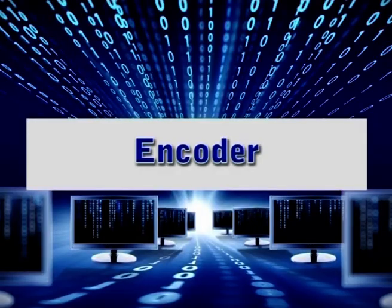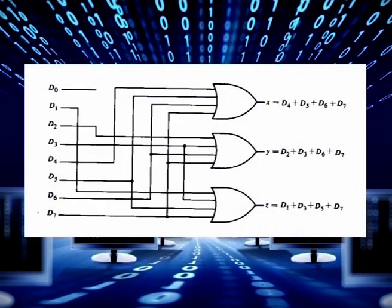Now, coming to the final topic for today, and that is encoder. An encoder is a combinational circuit which is designed to perform the inverse operation of the decoder. An encoder has 2 raised to power n input lines and n output lines. An encoder produces an n-bit binary code corresponding to the digital input number. An example of an encoder is the octal to binary encoder, whose truth table shows that it has 8 inputs, one for each of the octal digits, and 3 outputs that generate the corresponding binary number.